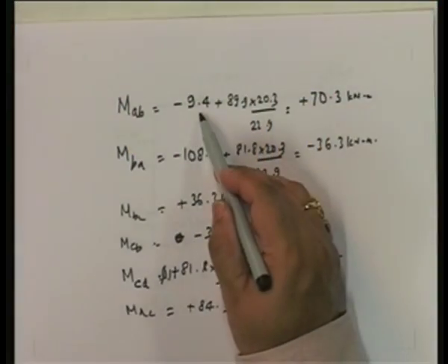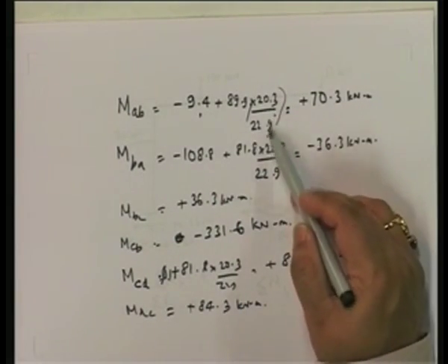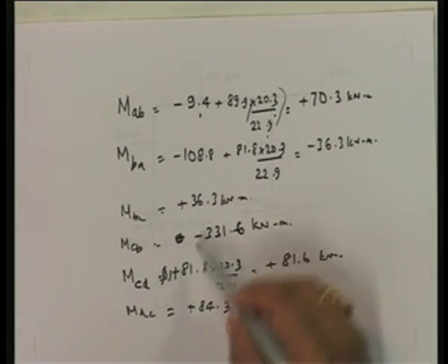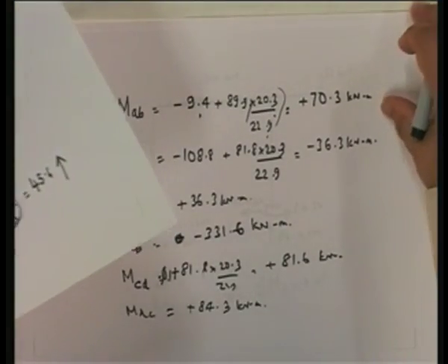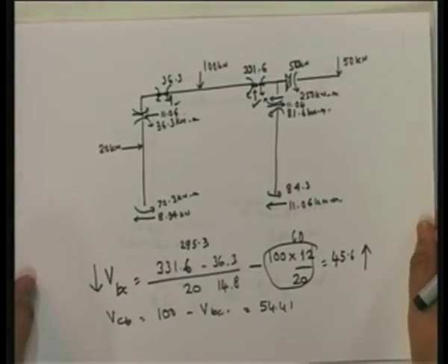Now that sway reaction and the no sway reaction, the total sum of the two reactions, have to be equal to 0, and because of that, when you put it all together, you add the sway and non-sway moments, corrected for the actual values. Once you get that, you've got the actual moments due to both the sway and the actual structure.